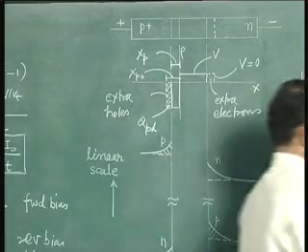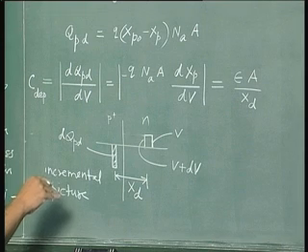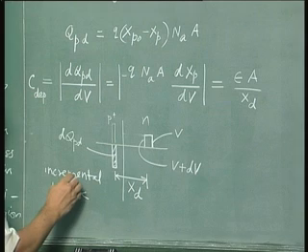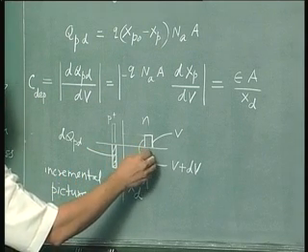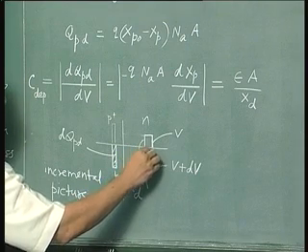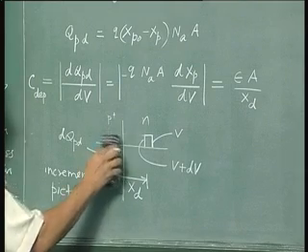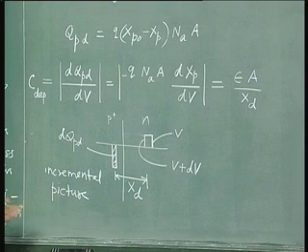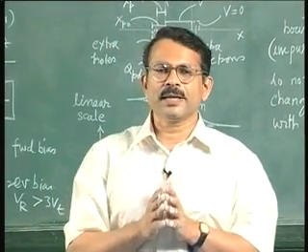If you want to show that more accurately, then you must show the dQpd as a rectangle on this side, and dQn, that is the change in the electron charge on this side, as a rectangle here. Here we must understand that what we are talking about is the magnitude of dQpd. So this is the magnitude, the shaded area. We don't care about the sign when we are talking of the magnitudes.